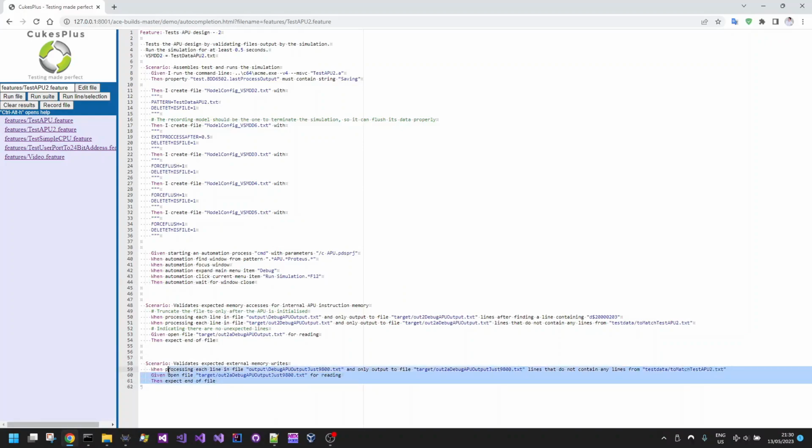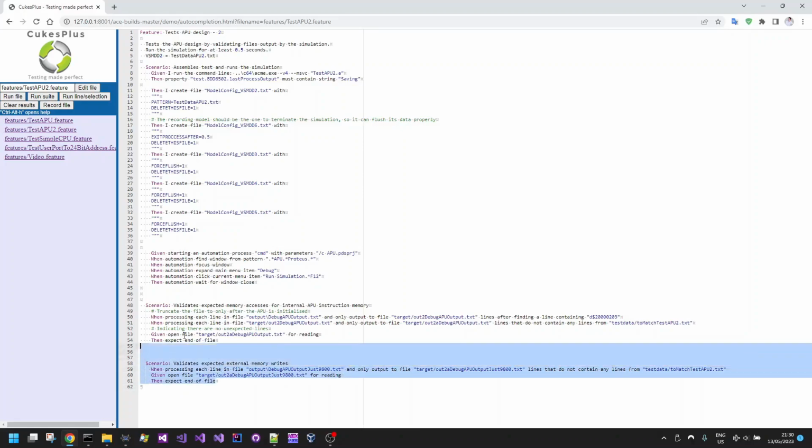And I'm doing another reconciliation here with the output sprite address range as well. So I'm checking the full video hardware external bus range, and I'm also checking a specific internal video hardware bus range, if you like, for the sprite registers, just to make sure everything is working correctly.